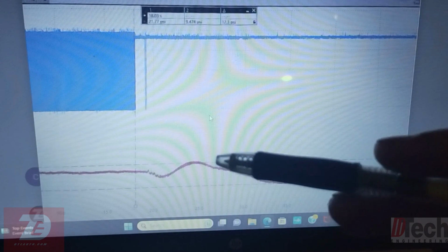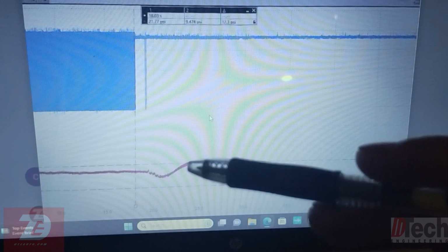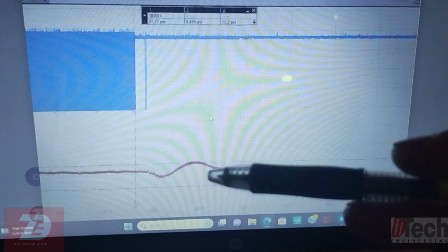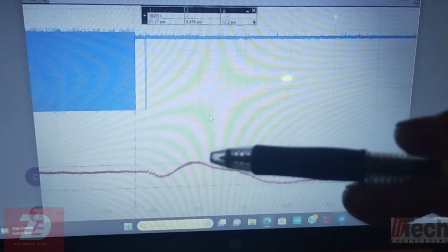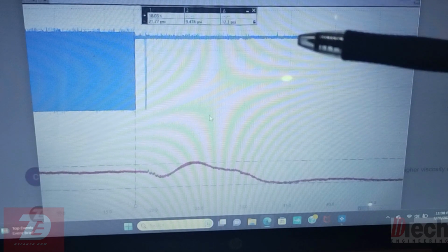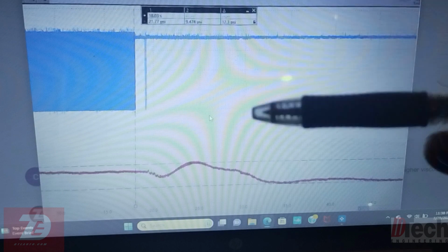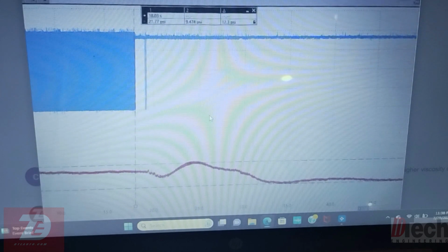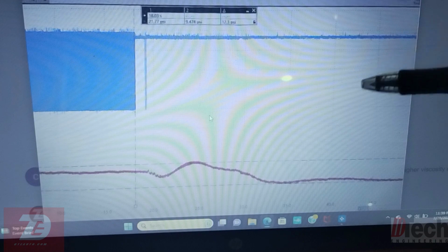You can see that the pressure actually shoots up and rises, and then past that point, still with no control, we are now mechanically shooting as much oil pressure as we can feed, because the oil control valve is in its full range to feed as much pressure as we can based off of those specs that I read to you earlier.